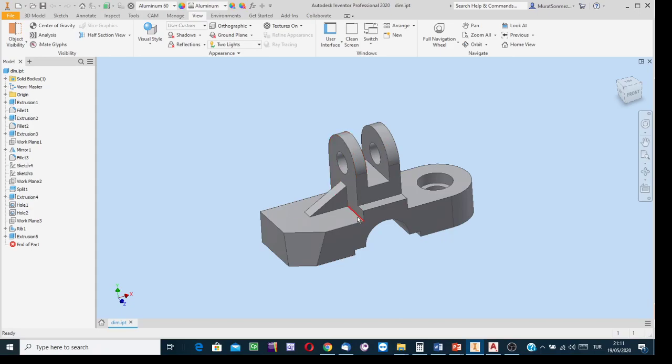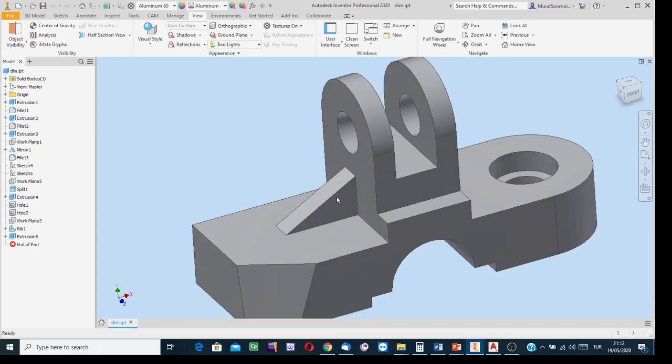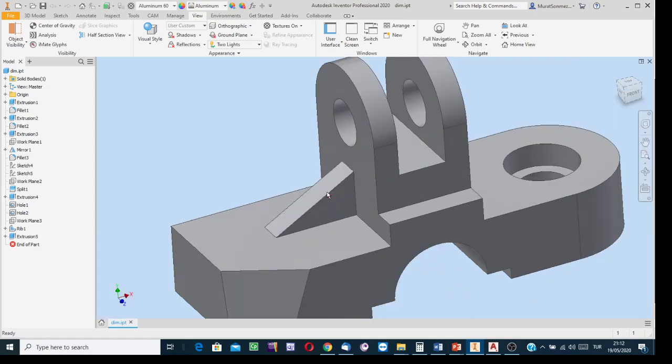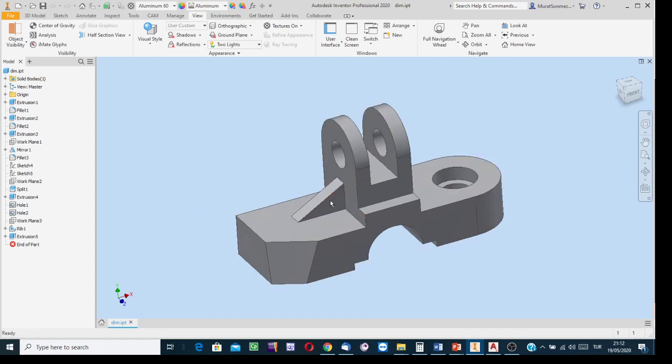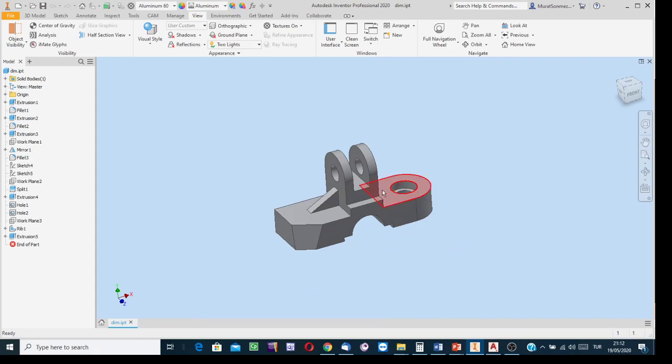And to make this intersection stronger against the forces that will be applied by the surroundings of this object, such a strengthening feature has been added. It is called a rib, you know. We have a triangular prismatic support here. It is to increase the rigidity and strength of this interior edge. That is the object, that is its geometry.